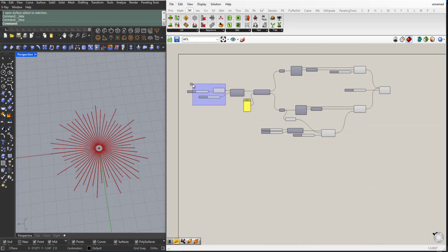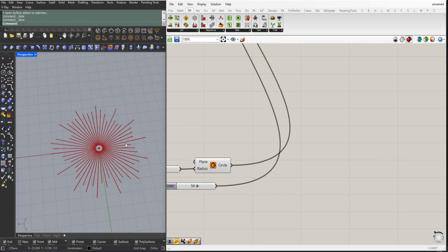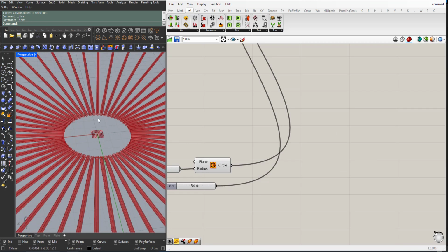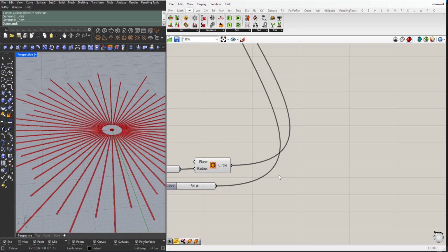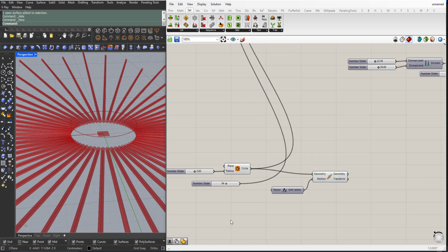So now let's take care of the mirror. So for this circle, first I will create a copy from this circle and move it up. So choose move, double click Z, unit Z. Choose a value like maybe 3 centimeters for now.